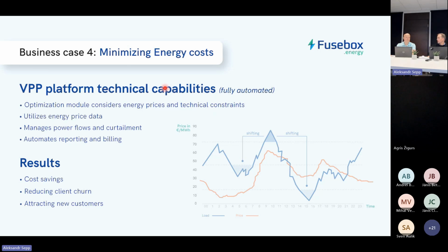It's as with this backbone, you can predefine how many times per day they wish to deal with the peak shaving and shifting. What should be the period between different activations? Can there be consecutive activations or 1 hour, 2 hours between? Should it be with some kind of a delay?